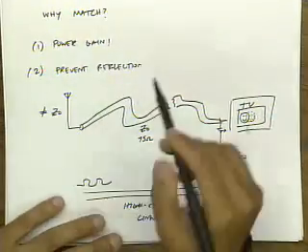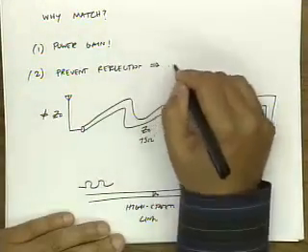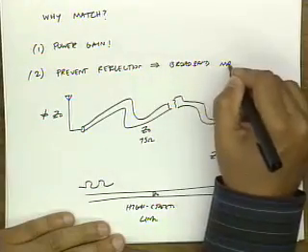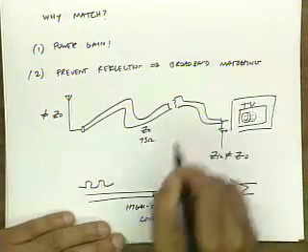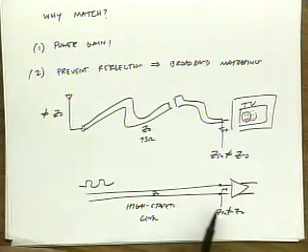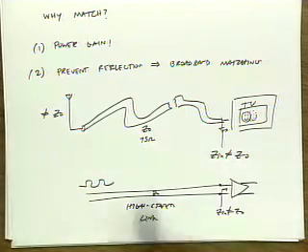What's a big difference between case 1 and case 2 is that we really would like broadband matching. In this case, the data signal is broadband, it's high speed. So we would like to provide a termination from DC all the way out to a few gigahertz, if this is a gigabit per second kind of link.